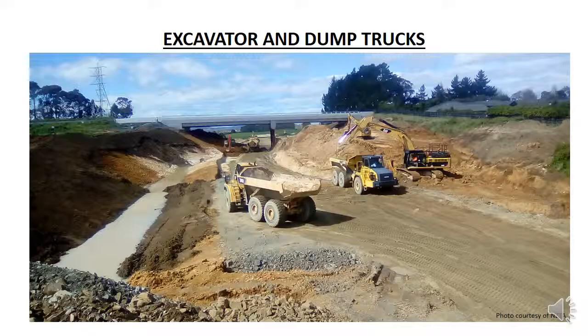This photo shows trucks being loaded by an excavator. One truck is being loaded while another waits. Note that the waiting truck is out of the way of the truck being loaded, but it will be able to move quickly into the loading area when it is its turn to be loaded. This means it takes less time to load trucks, and so you are moving more soil each hour. Making sure you are maximizing productivity is an important part of earthworks planning. Another part of the planning is to make sure that you have enough trucks to keep the excavator working all the time. So matching the plant is another important part of earthworks planning.